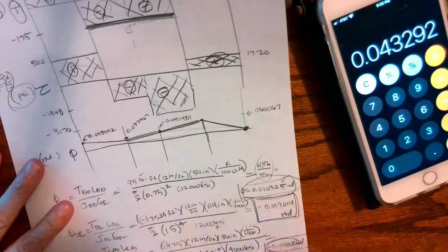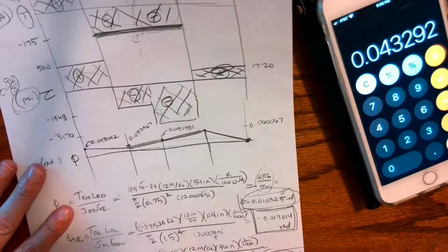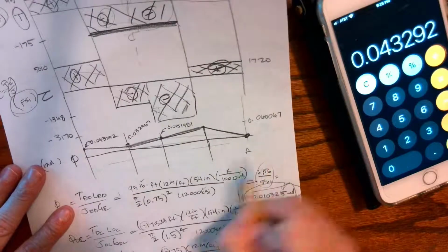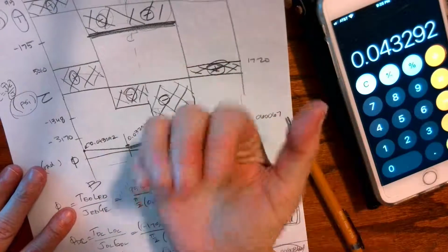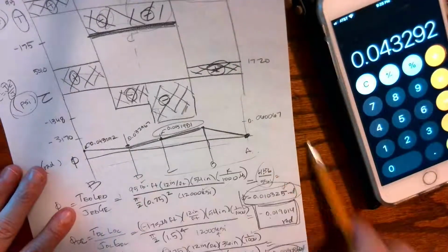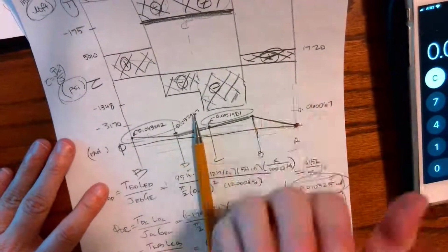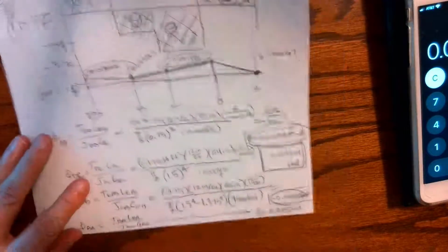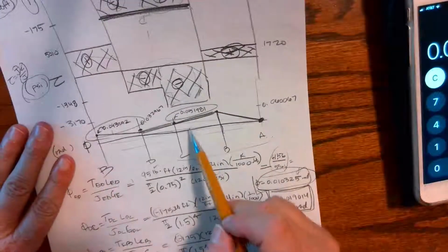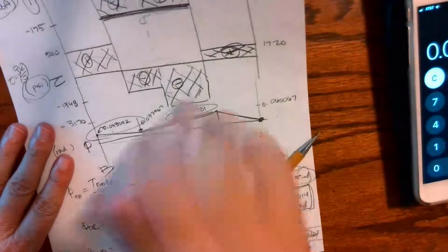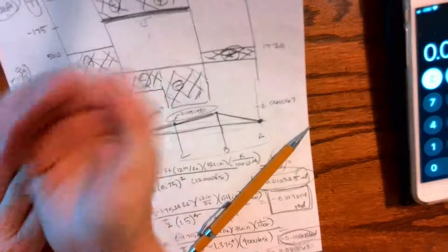Okay? So if I want to know the angle of twist from A to C, remember here's A, B, C, D, E. The angle of twist from A to C is a positive angle of twist. So we're twisting towards ourselves coming from the right. If I want to know the overall angle of twist at the end of the beam, it's positive, so it's coming towards me, 0.0432. So even though we had these negatives right here in the middle, because of our material properties and our geometry, we never switch back over to a negative angle of twist in a shaft. Everything stays positive. It's just a little bit different degree of positivity as we move back down.